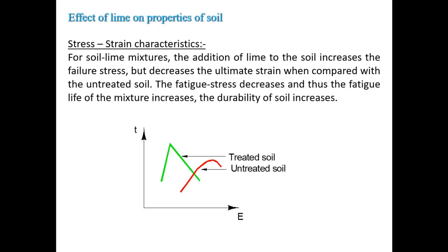Next one is effect on stress strain characteristics. For soil lime mixtures, the lime addition increases the failure stress but decreases the ultimate strain when compared with the untreated soil. The fatigue stress decreases with lime stabilization and causes increase in the fatigue life and durability of the soil.